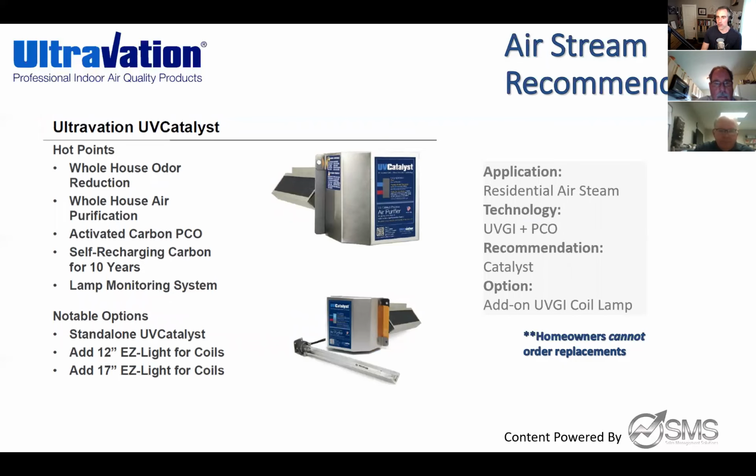We even make a zero ozone version of that. There's no ionization on it, but instead of all the metal surface around the bulb being treated with the titanium dioxide to create PCO, we have 3 full strips of carbon, so the carbon actually absorbs the ozone. So this is technically a zero ozone product, but they're both generating PCO. It's just this one absorbs itself and you're good to go.